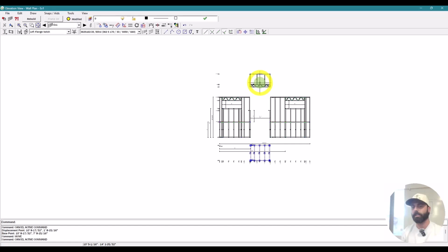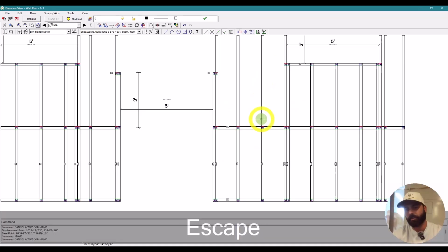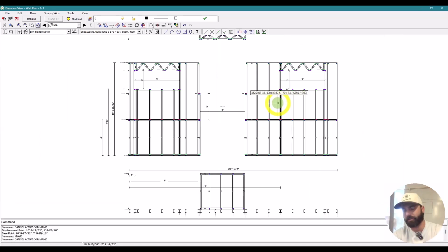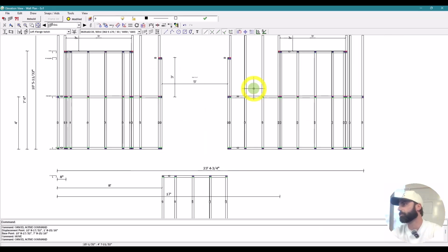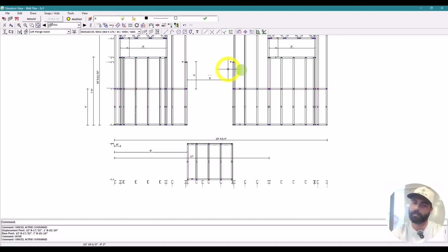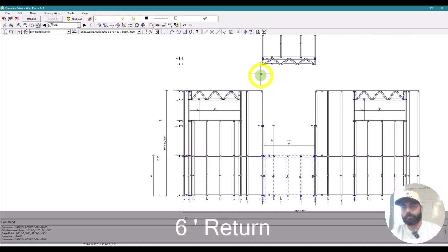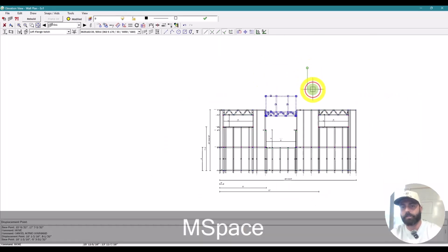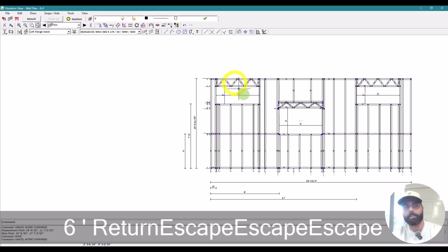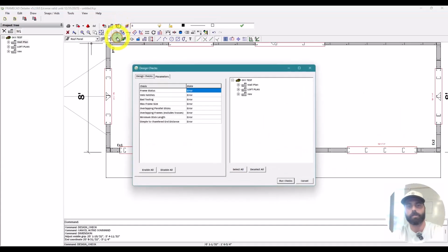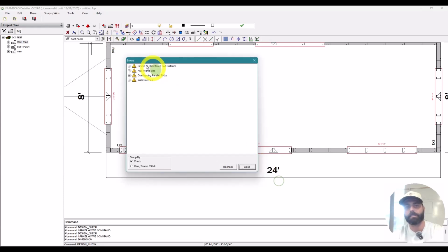How do you adjust this for roofs? Roof panels are going to be the same. So you can run checks and balances in the software. If you set max frame sizing and frame weights for yourself, you can run checks. I still run analog checks all the time. It's not perfect, but if you say I want my max panel size to be 8 feet by 12 feet, anything that exceeds that will show up in this oversized max frame size. So it's saying it's too big, it's too big.